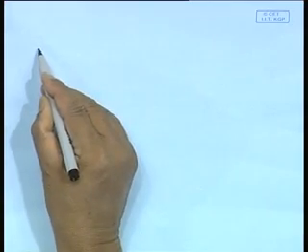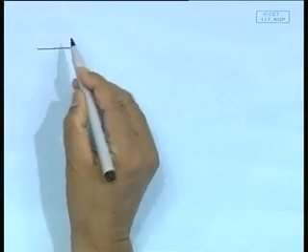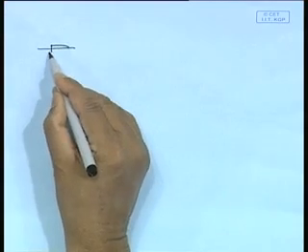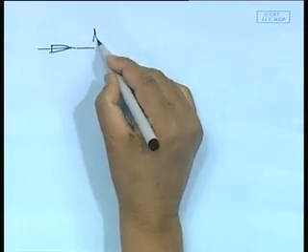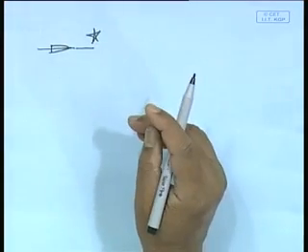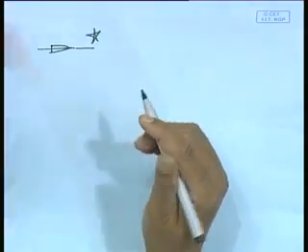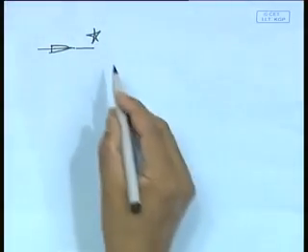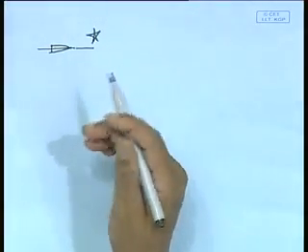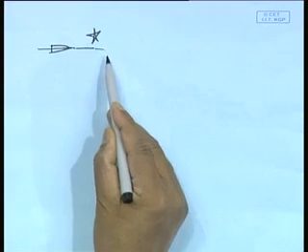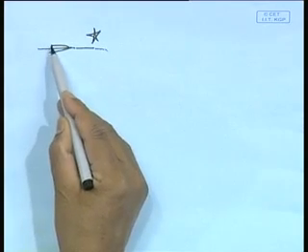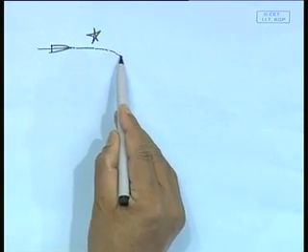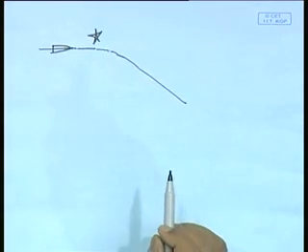There is a ship coming here. Here I give a disturbance, a large disturbance, let us say I give a push. Then I give a push and leave my hand, just like our roll, where I rolled it to 5 degrees and left my hand. What would happen? There are various possibilities. The ship, with no rudder, remember there is no rudder, can take a straight line course.